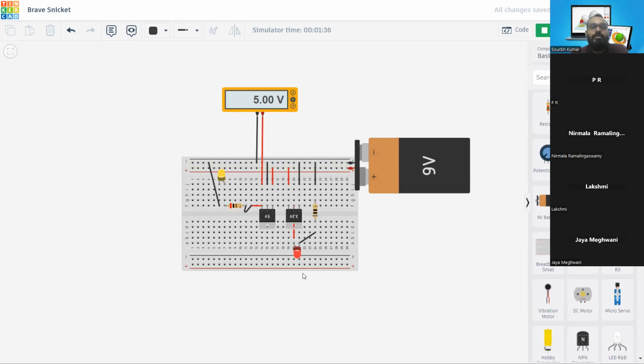The LED component I'm utilizing to show you the conversion process does not work on 3 volt or 5 volt. We must reduce the voltage to 1.5 or 2 volts, approximately 2 volts at some amperage. That is why I utilize the resistor in between, to reduce the voltage further after receiving 5 volt or 3.3, even though 3.3 volt is not good for the LED itself. So you must take care of those things while building any circuitry.